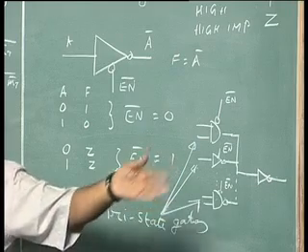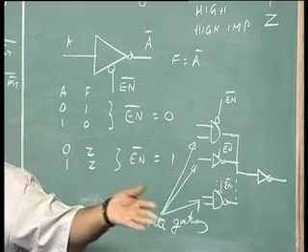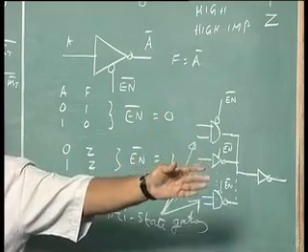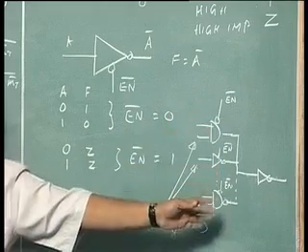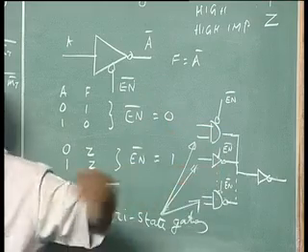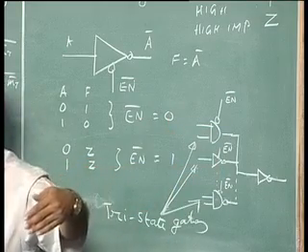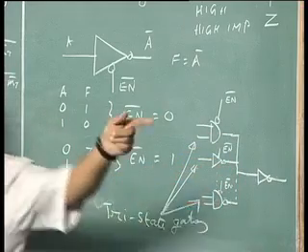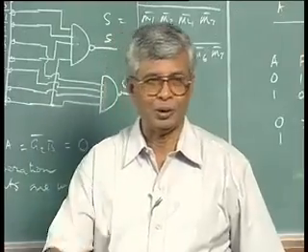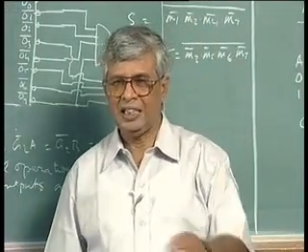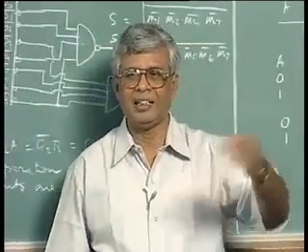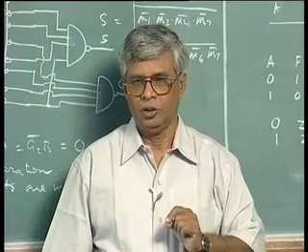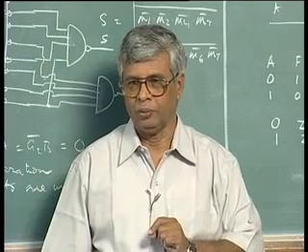It transports a lot of things at the same time, right? Many people can join the bus and then go. Many signals can join and go. So the common bus is there. All these outputs feed into a common bus, but the input will be used for only one of those signals. So I have to disconnect the other inputs from the bus. Physically disconnecting is not possible, so I electrically disconnect the other inputs which are not required at a given time.